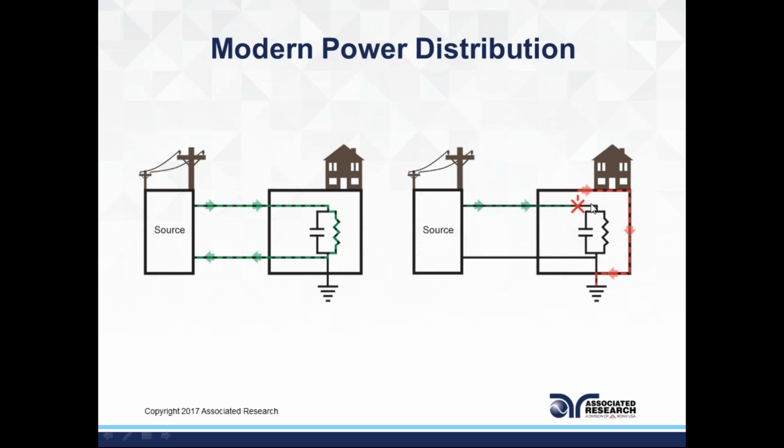And in this case, if the fault has occurred, there should be some system that deactivates the voltage coming into the house. And this mechanism is usually the breaker panel installed in your house, or, if it's a big enough short, it could also be a breaker that's tripped at the utility station, which is pretty rare.